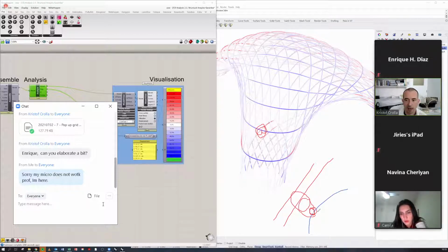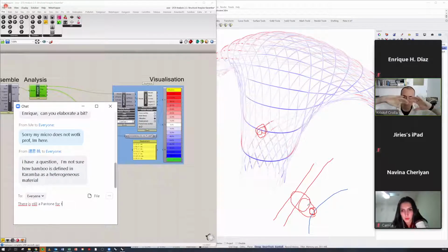But this becomes a sliding eyelet. Ideally it would become a sliding eyelet, because then you can guarantee that you have tension throughout your entire system here. What you need to prevent is that the metal will cut through the bamboo, or make it collapse, or even just from the general movement of the pavilion, that it doesn't start to saw through it. So that's why working with an eyelet like this could work really well. And then at the very end, you add your typical tension system to tighten up your cables like that. That could theoretically work.